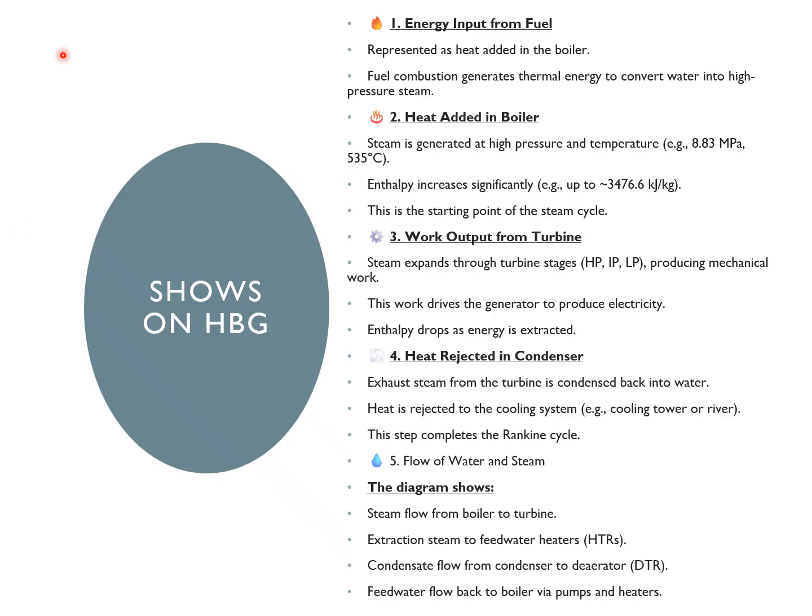So the major equipment contributions here are the boiler and steam generator, condenser, feed water, control valve and throttle valve. You also understand about the SSR, steam seal regulator, which maintains sealing steam pressure in the turbine gland.